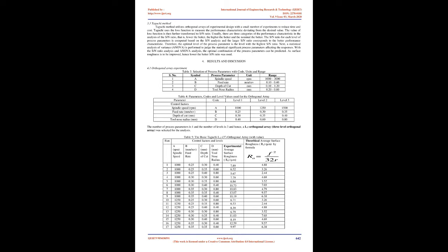Siho MT and Biju N [4] applied Taguchi parameter optimization method to determine optimal process parameters. Depth of cut and hardness of material had less contribution on surface roughness. Feed rate was the prime factor for surface finish. Ilhan Asildurk and Harun Akis [13] studied optimal turning parameters based on the Taguchi method to minimize surface roughness. S/N ratio and ANOVA methods were used to investigate effects of cutting speed, feed rate, and depth of cut on surface roughness. Results indicated that feed rate had the most significant effect on surface roughness.